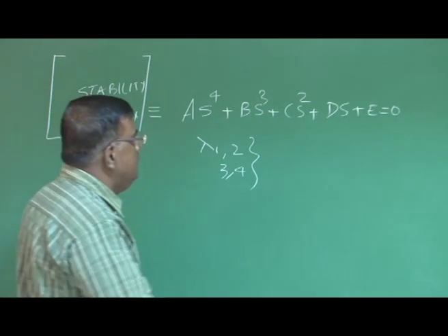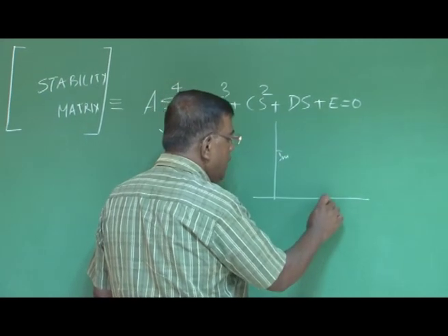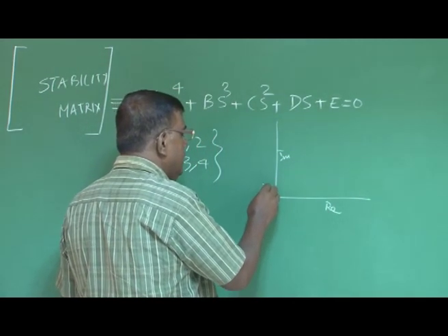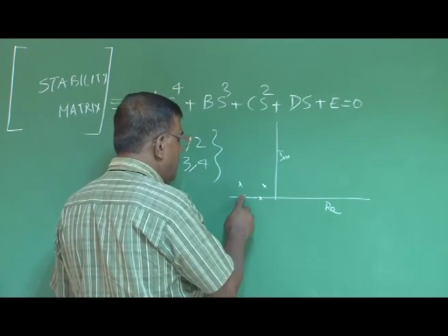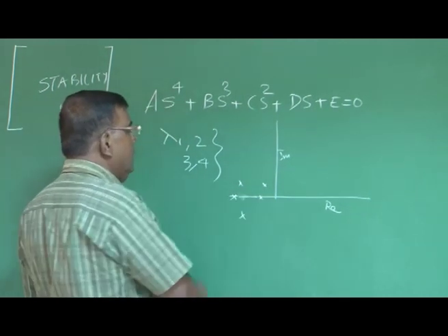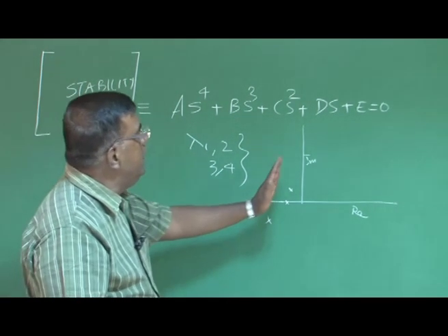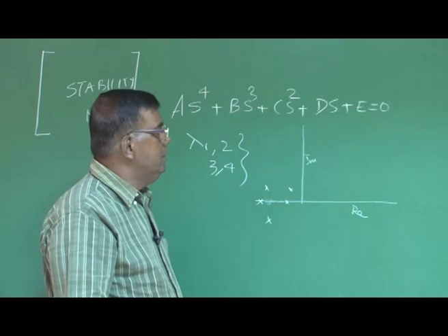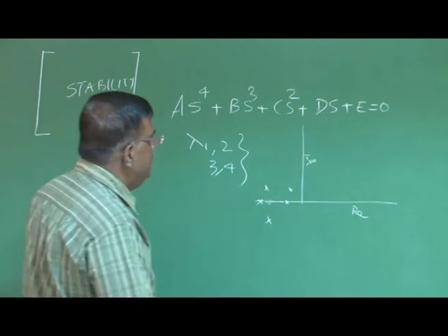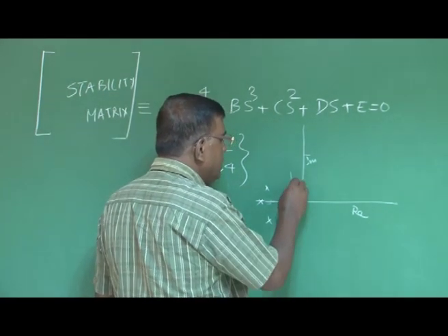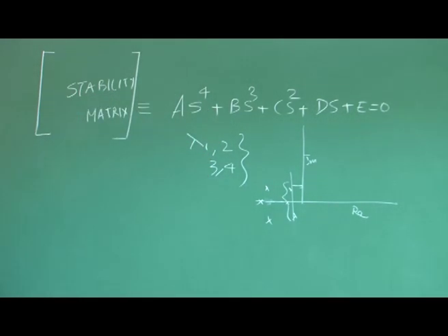We also realize that if we plot the imaginary and real parts of the roots, we wanted them either this way, or maybe on the real negative side. What was important is that roots should lie on the left half plane to ensure that there is convergence. But the question comes: how far from the real axis, and what is the magnitude of this if it is a complex conjugate? That depends upon what?